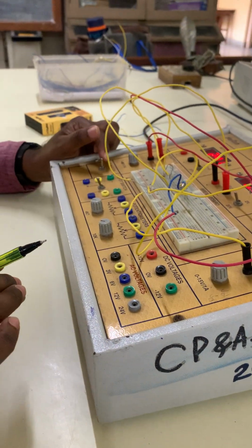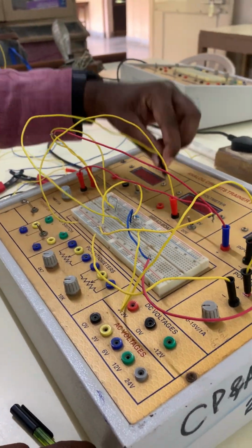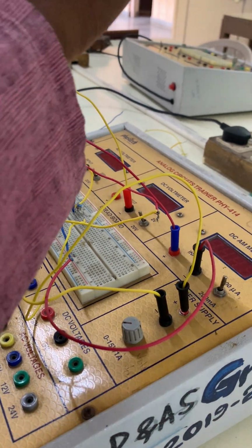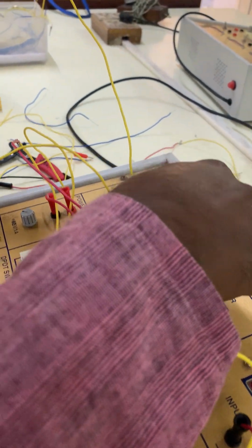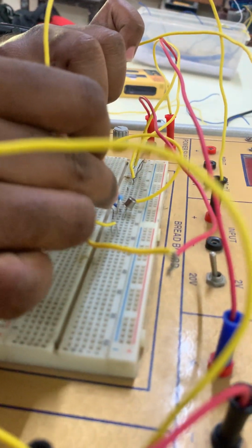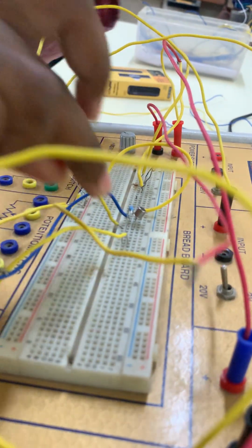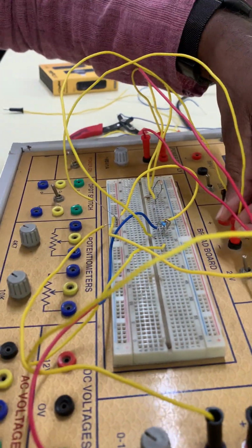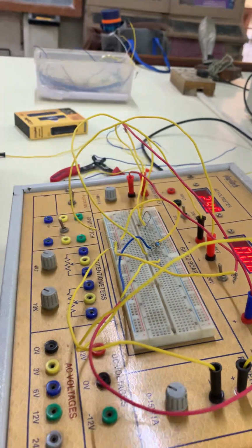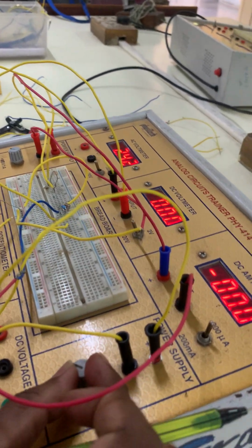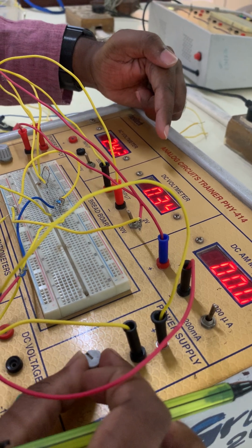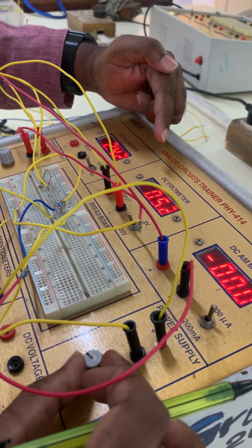Similarly, now you remove this input voltage and set the output voltage. Where do we have to keep it? Wherever the collector is. Collector is here, correct? So now you keep this at the collector, switch it on, and set VCE. How much do you have to set? Last time it was 0, now this time you have to apply 0.5.